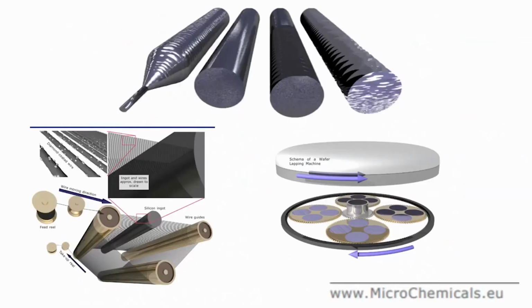Now, this is how it will look. You have these boules, you can see here. When you do the edge, you remove the edge by grinding or trimming, then you have this one. Like I said, a diamond coated wire is used to slice the wafers from the ingot. After slicing, you can use the lapping machine. You can see here a lapping machine to lap the wafer. After lapping, there is chemical etching and then polishing, and finally the inspection.